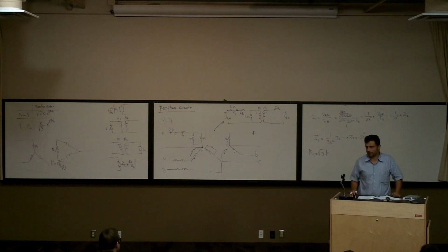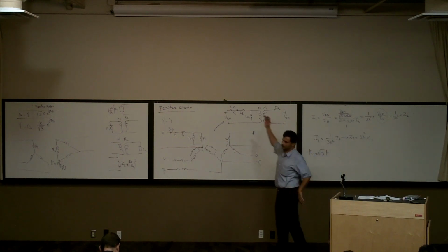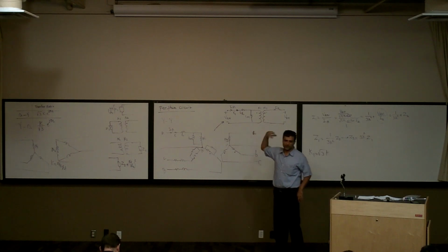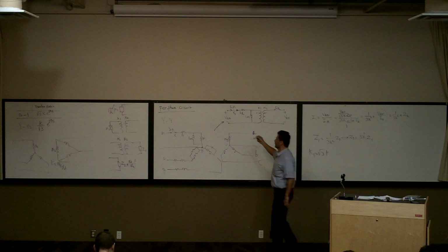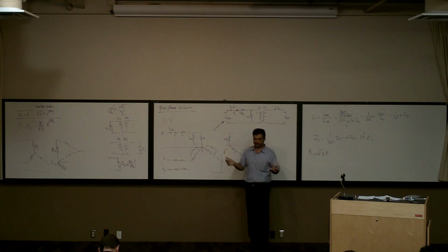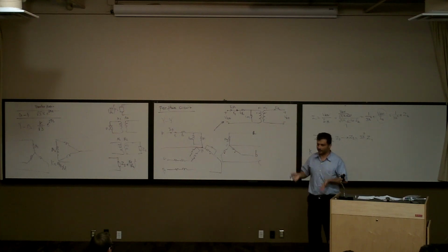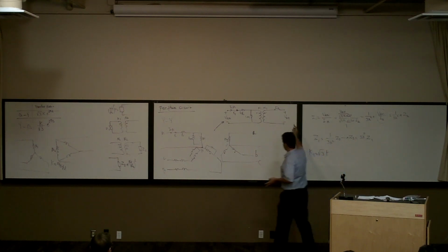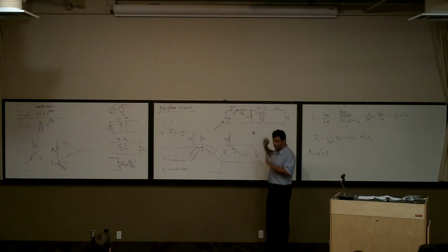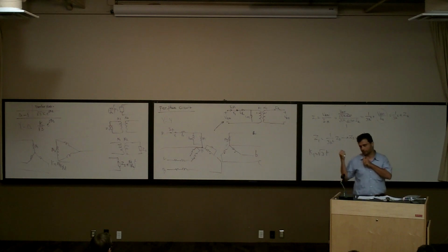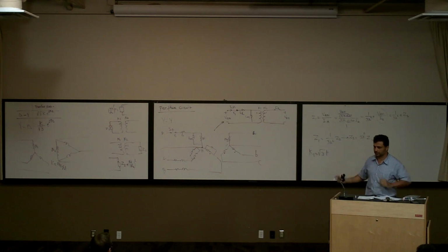And whatever, for example, if I need IB, I calculate IA, just shifted minus 120 degrees. Or if I need IC, the same thing. If I need VAB, I have a VAN here, right? VAB is going to be the line voltage, the square root of 3 times this one, and add the angle, right? So basically, solving this circuit is going to give me all I need. Whatever else you ask me, I can calculate based on the result of this one. So this is very simple. This is exactly like the single phase transformer. We talked about it for a Y-Y connection.